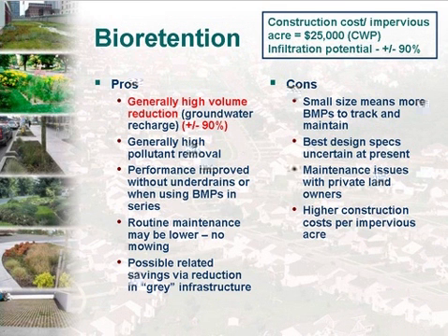So just looking at the pros and cons here, just to continue with our idea, of course, we've got this high volume reduction. And again, as we've mentioned several times in this webcast, volume really may be the thing that you need to worry about. In that case, some of these low-impact development ideas can really help out, particularly with those smaller storms. And with that often comes high pollutant removal, and we'd like in the future to be able to tell you exactly more about that, and we will by gathering up those studies.